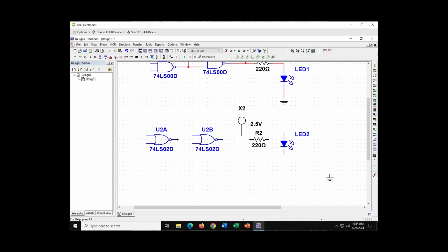And let's go to our NOR gate, and we have an inverter, so our NOR and an inverter becomes an OR gate. So we're going to go connect our resistor, our probe, and since our unique condition on this one is 0, 0 equals 0, that is going to be sinking.